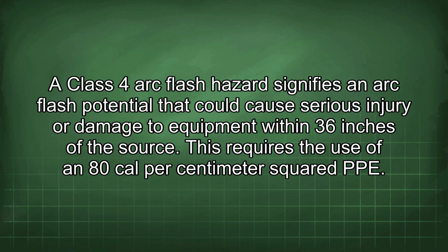A Class 4 arc flash hazard signifies an arc flash potential that could cause serious injury or damage to equipment within 36 inches of the source. This requires the use of 80 cal per centimeter squared PPE.